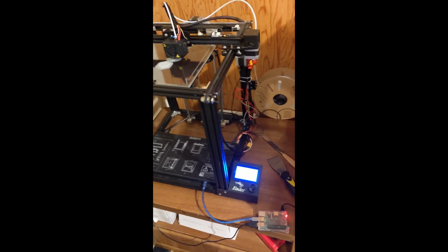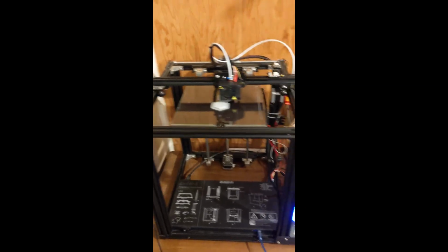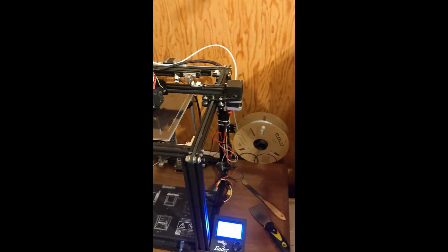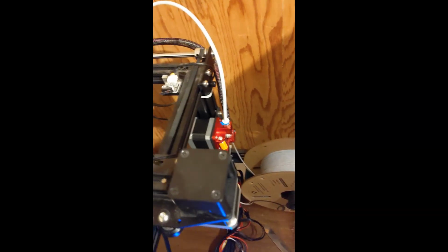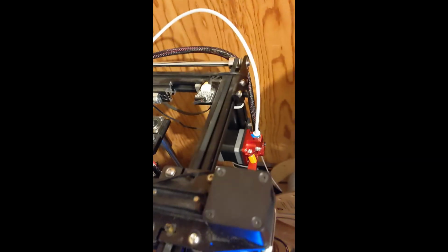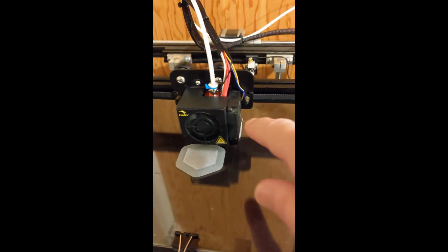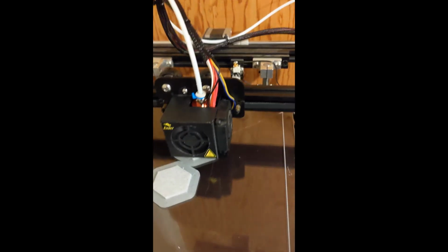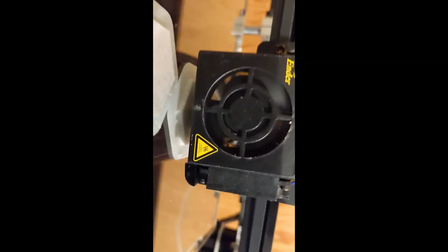So here's my 3D printer running right now. It's printing something that we're going to redesign later. But most printers that work by adding layers of filament are basically this design. So you have a spool of plastic. It looks like thick fishing line, or what you put in a weed whacker, and it goes through a little mechanism that pushes it through this tube. It goes into this device, which has a heating element which gets heated to around 200 degrees Celsius, melts the plastic, and then the plastic just comes out of a little nozzle.